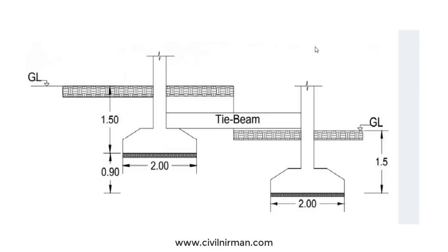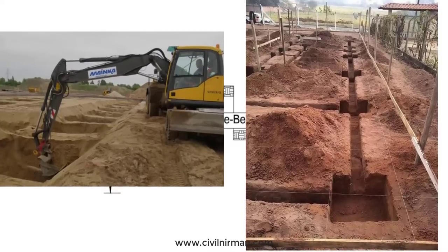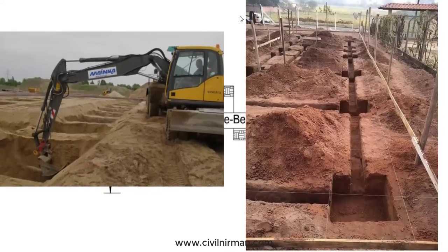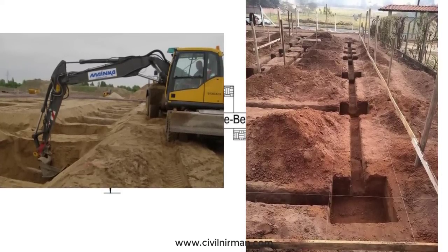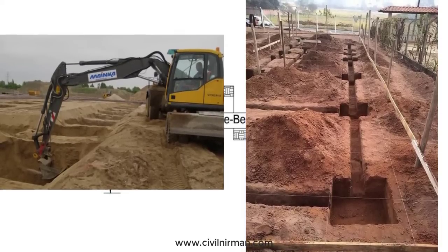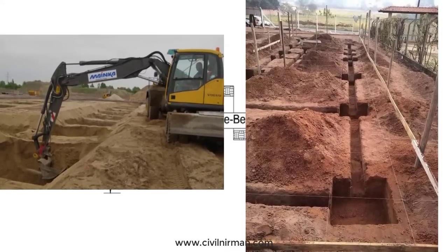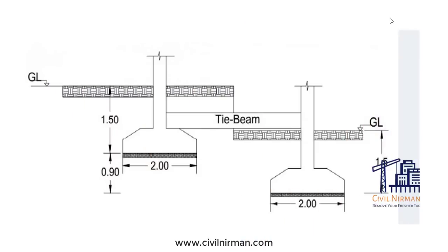Now see, it's a critical element of the drawing as it provides a clear reference for the builders and contractors to understand the required dimension and depth of the excavation. It has two main purposes: the excavation line outlines the outer boundaries of the foundation and helps in defining where the foundation will be built, ensuring that the builders dig within the correct area. Now you have a clear idea about the excavation line as well.